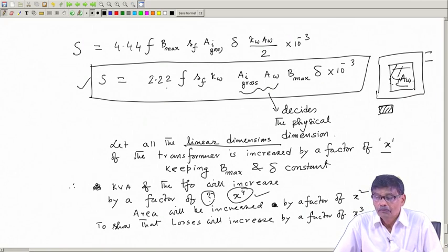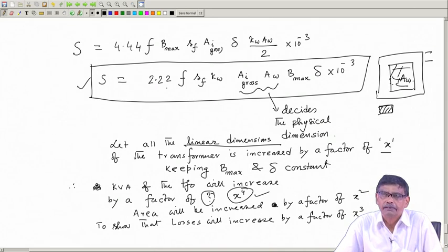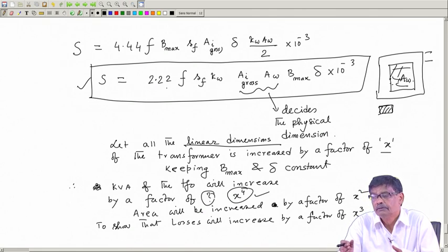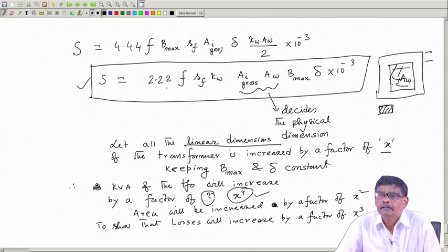Now, see, if you have a transformer in your lab, maybe 1 kVA, 3 kVA, you will find no extra cooling arrangement is necessary, because the natural cooling by air comes in contact with the coils, everything is open, windings you can see, only terminals come out from the LV-HV winding, and heat generated in the coil and the core will be dissipated in the air.